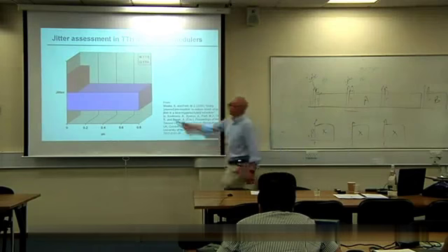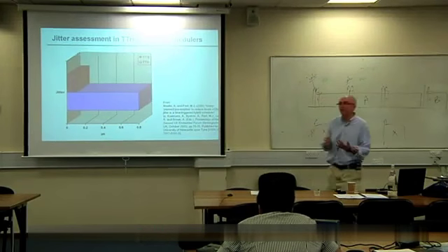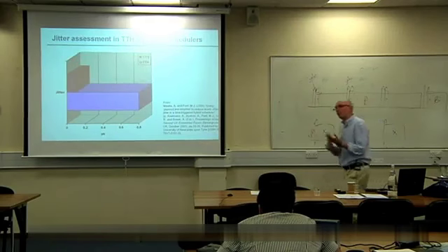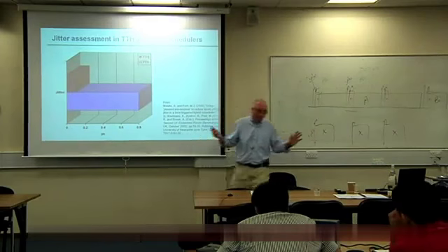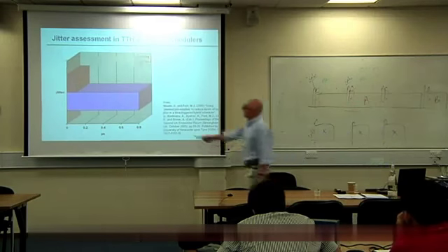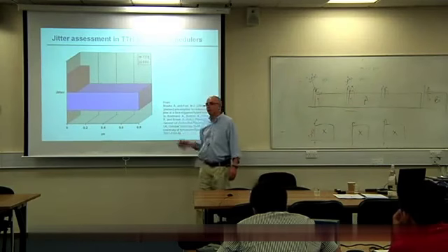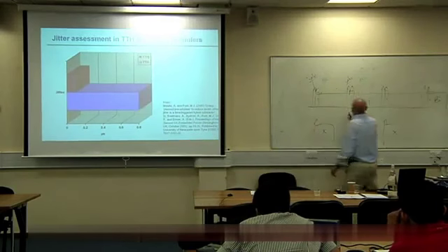And this is the kind of jitter levels you're getting. It's not an 8051, it's quite a reasonable performance, a 32-bit ARM7 based microcontroller running at about 60 megahertz or something. Pretty fast device, and we're getting 0.8 microseconds of jitter from this task.